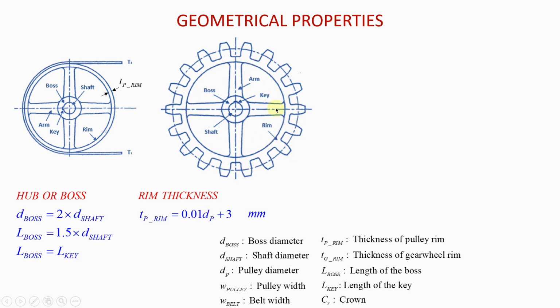And then you also have the thickness of the gear rim, okay? The gear wheel's rim. Okay, and that is that length there. That's the thickness of the gear wheel's rim, okay? That length here. And the equation for it is 0.5 multiplied by the circular pitch, okay?